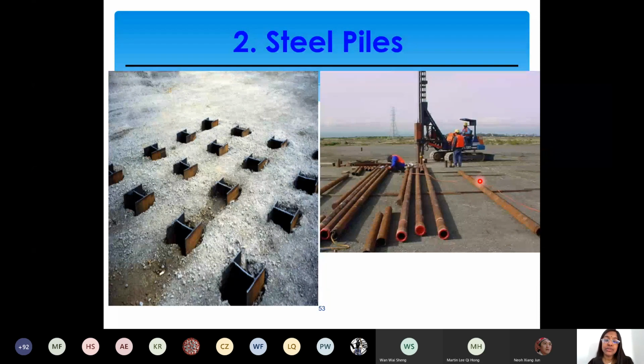So try to use precast concrete by choosing proper strength and grade. By increasing the grade, you can achieve the strength. I think you would have studied in other material RCC lessons how you can improve the grade of the concrete and the corresponding strength. So choose the proper concrete so that you can replace steel at these places, moist conditions, swampy areas, and so on.